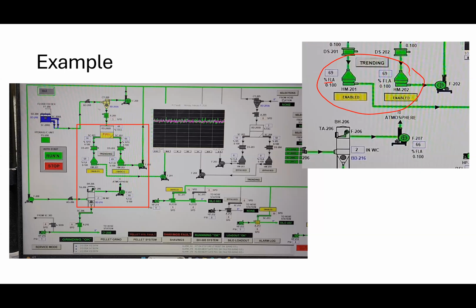All right, so let's say the motor on the left, for sake of argument, was rated for 100 amps, and this one was rated for 200 amps. If the readout said on one side 86 amps and the other one said 122 amps, it's just not very clear what that means in a general context. So usually we just talk in terms of the percent of the rated value. Does that mean no matter what the size of the motor is, the percent value means something to somebody?